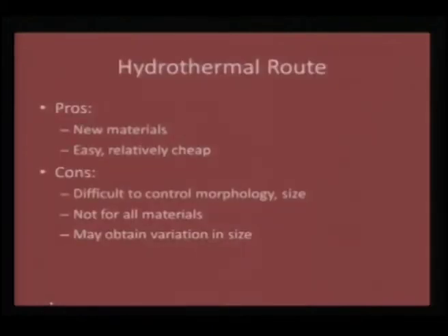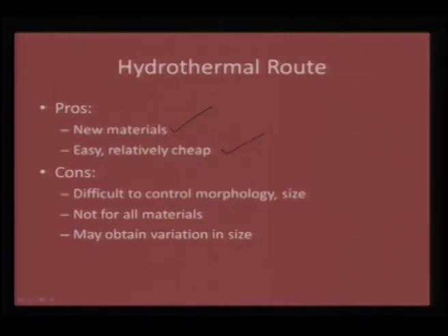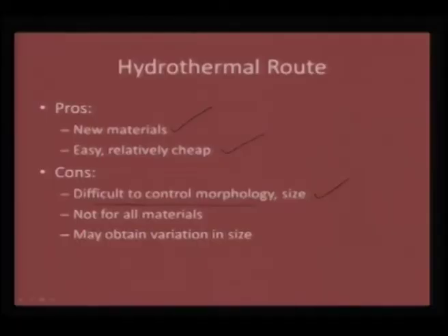Lastly, I just want to conclude by talking about the pros and cons of hydrothermal synthesis. What are the advantages? One is you can discover a wide range of new materials, because every particular reaction will bring about a new metastable phase, and it is easy and relatively cheap, and can be done experimentally on a lab scale. And the difficulties are we need to understand the chemistry that is operating. It is not just generating very high pressure, but we need to understand beforehand the nature of the components and additives that you are using. Therefore, we need to have knowledge of how to control the morphology and size.